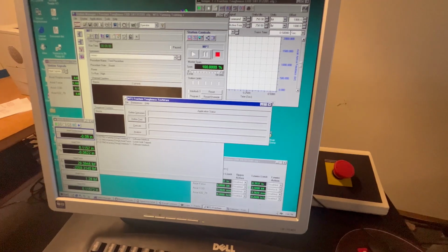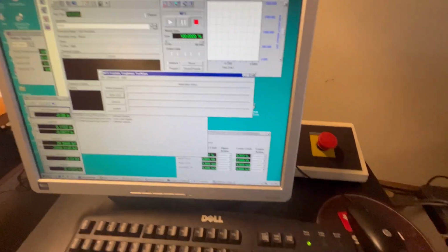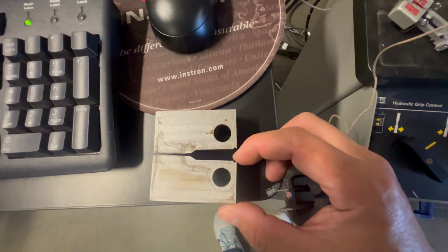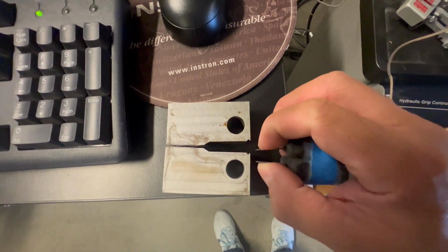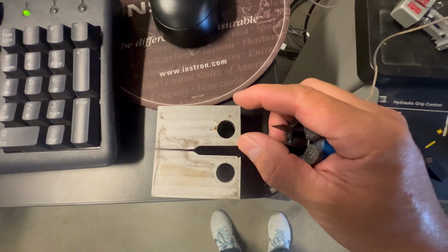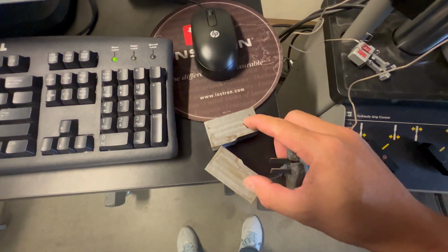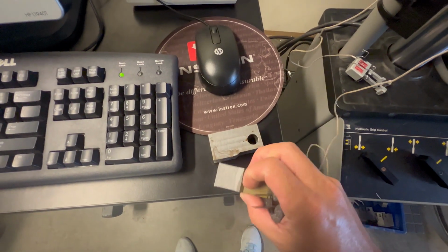The testing software will stop the pre-cracking cyclic load after detecting the pre-crack reaches the target length. Then, the K1C test needs to be executed by applying a constant load until the specimen breaks into two pieces.